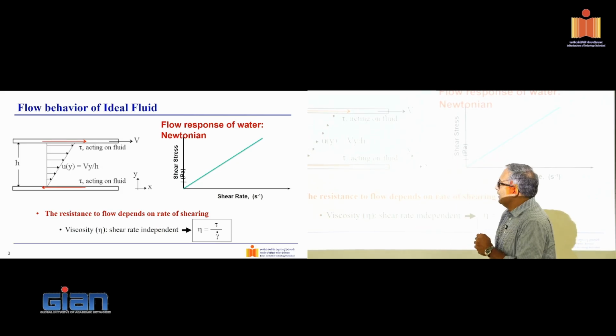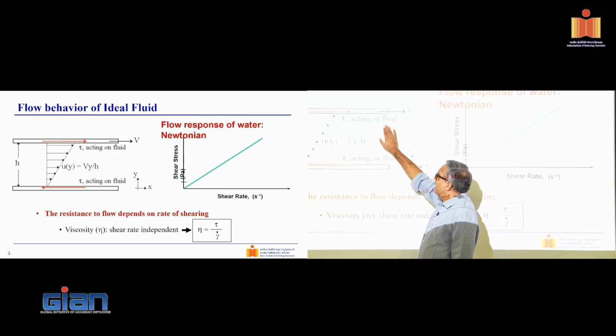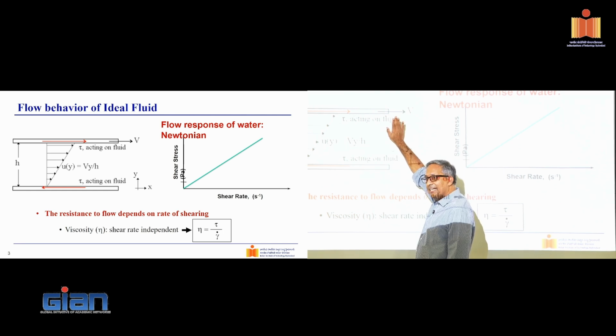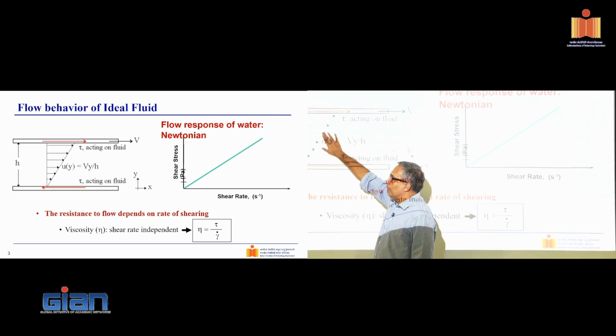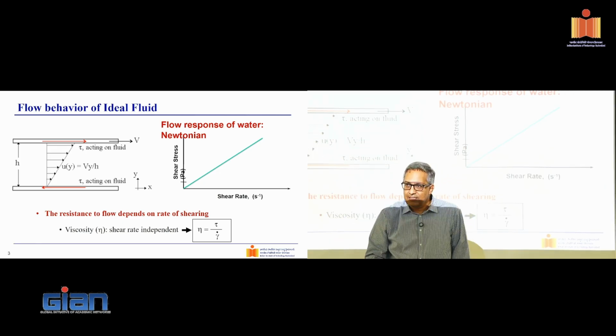the rheometer. So even in an idealized situation like what we have here, I can measure the force that I'm applying on the plate and the velocity with which this plate is moving. What I don't know is what is the stress that is developing here. I can only infer it. And I do not know what is the strain rate at which this is happening.